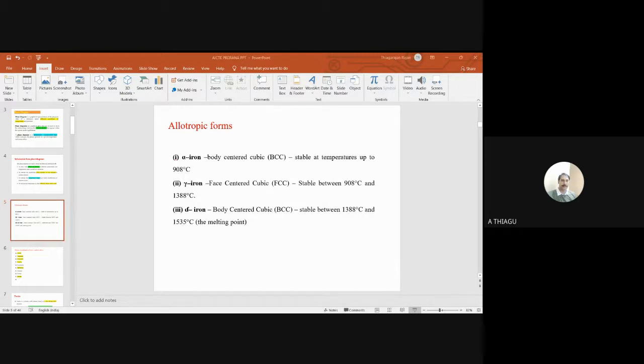So this is a particular slide which I want to show to you. You have to heat the specimen at 750 degrees for 3 hours. The entire structure will be austenite. Is it right? So alpha will be produced. Then the alpha is going to convert into pearlite. Pearlite is nothing but the formation of ferrite and cementite.